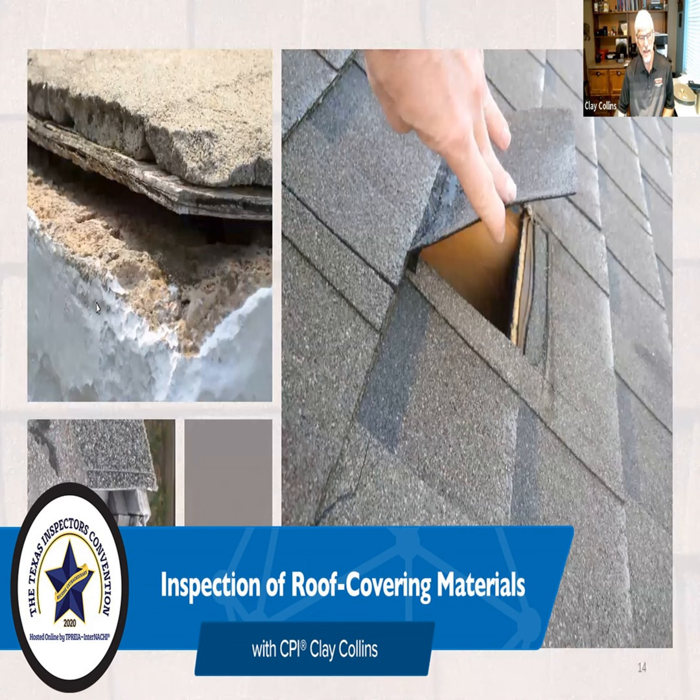When you're looking at the shingles themselves, what you're seeing here is a pattern for a high wind area and a pattern for normal. The normal has 4 and the high wind area has 6. Now keep this in mind, and I don't want to turn this into a discussion of windstorm, but 4 nails will meet the requirement for wind load areas, but it may not meet the manufacturer's requirements for purposes of warranty.